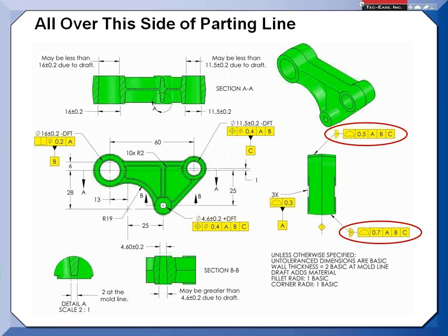You know, I look at those as design guides. So if you have a part that's 10 inches long, go to those charts and see what kind of tolerance you need over the 10 inches. And make that your largest tolerance. And then tighten up tolerances right up on the field of the drawing only where you need to. So what if you give a little more tolerance than the guide says as you get closer to an origin? If it doesn't matter, manufacturing will love you.